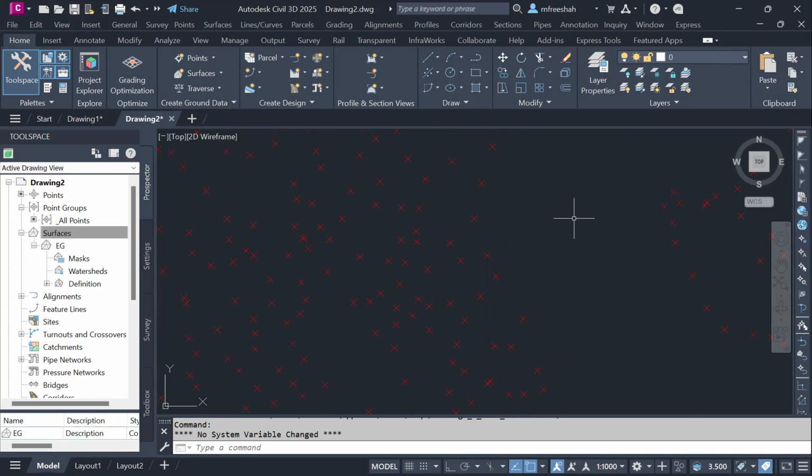So what will the surface do? The surface will help you create the relation between the points, based on interpolation, and give you the information for the missing parts or the gap areas. So every point on the surface, if you stand here after creating the surface, you will see the elevation. If you go to gap areas, areas without points, you will know the elevation if you stand like that.